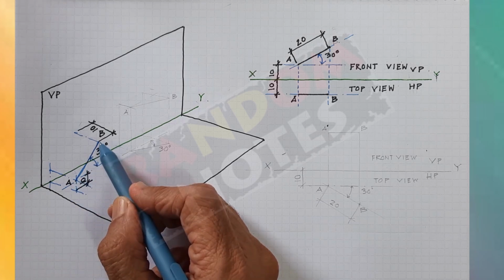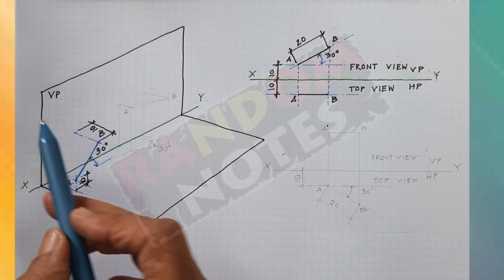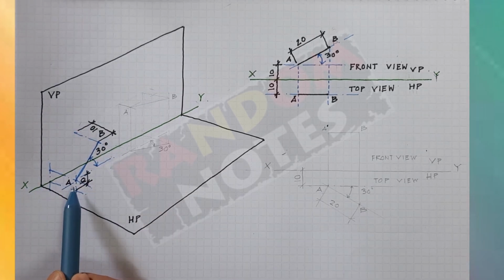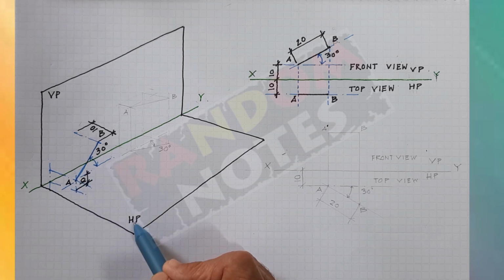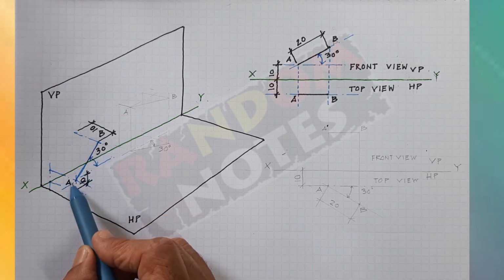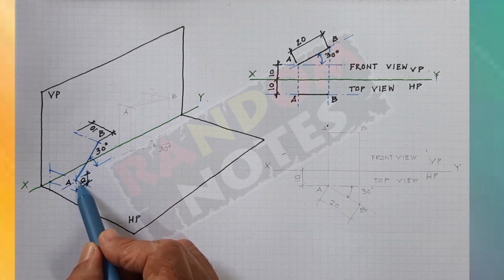We have a line of 20 mm length which is parallel to the vertical plane and it is 10 mm away from the vertical plane. This line is inclined to the horizontal plane at an angle of 30 degrees and the point A is 10 mm above the horizontal plane.